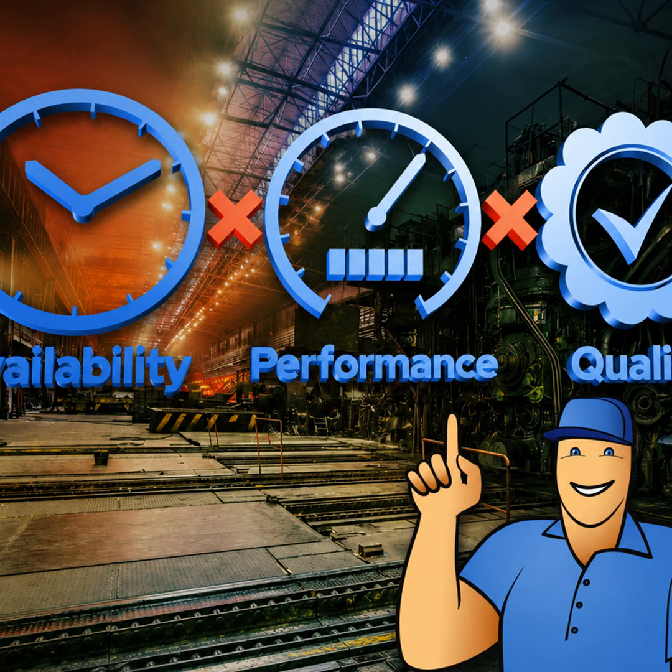Startup losses are those that occur before production gets into full swing. For example, the first pieces after a changeover might not meet spec. These first pieces are often used to dial in calibration and are test pieces. Or sometimes when heat is part of the process, equipment may not have warmed up enough for the first few pieces.